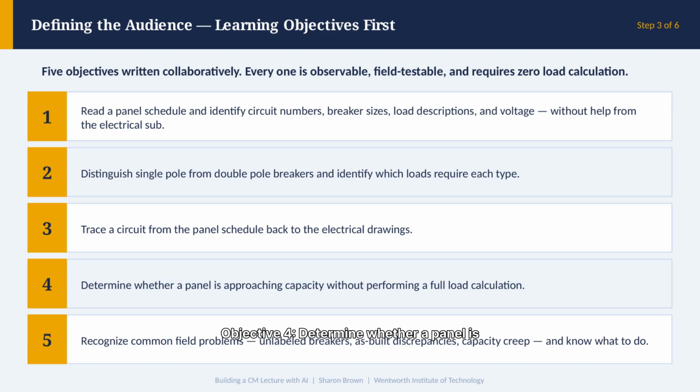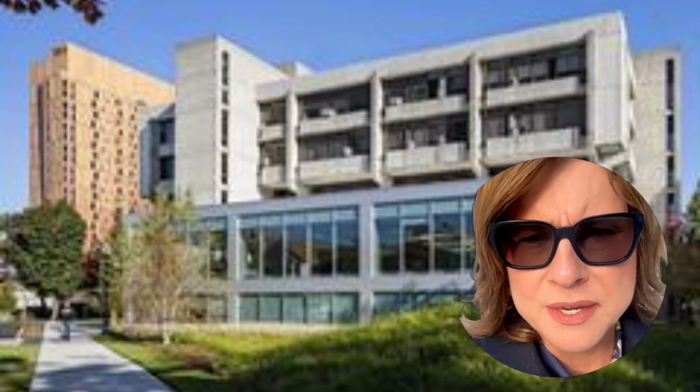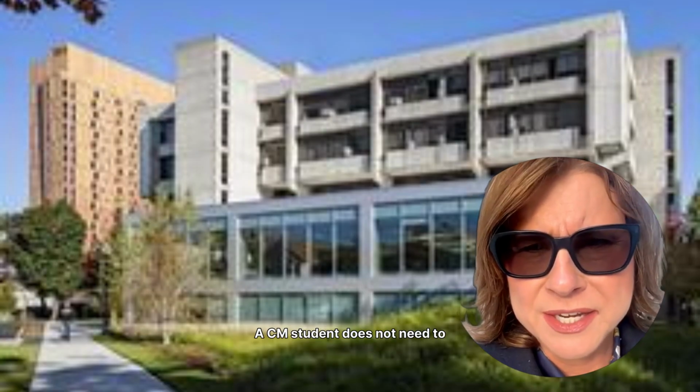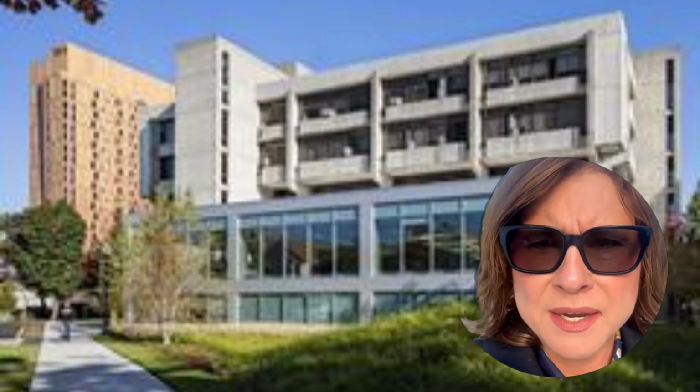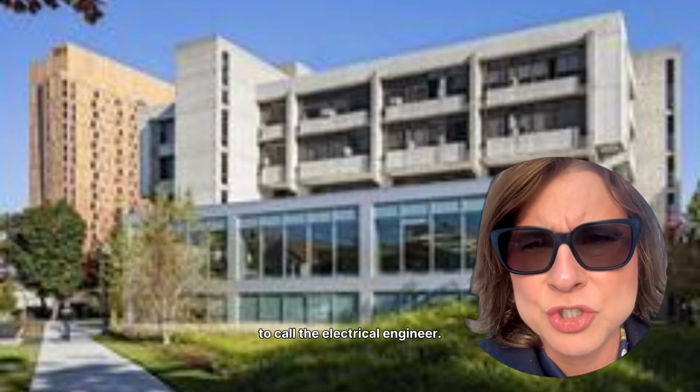Objective 4, determine whether a panel is approaching capacity without performing a full load calculation. Objective 5, recognize common field problems, unlabeled breakers, as-built discrepancies, capacity creep, and know what to do. That fifth objective is the one that matters most for this audience. A CM student does not need to calculate panel capacity. A CM student needs to know when to call the electrical engineer.